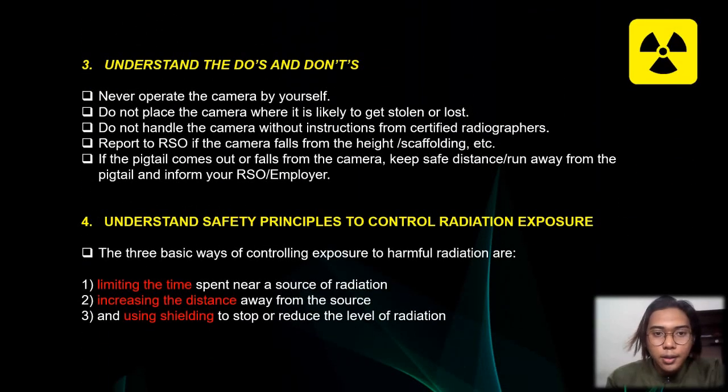Okay, third, understand the do's and don'ts. First, never operate the camera by yourself. Do not place the camera where it is likely to get stolen or lost. Do not handle the camera without instruction from certified radiographers. Report to the RSO if the camera falls from a height or scaffolding.